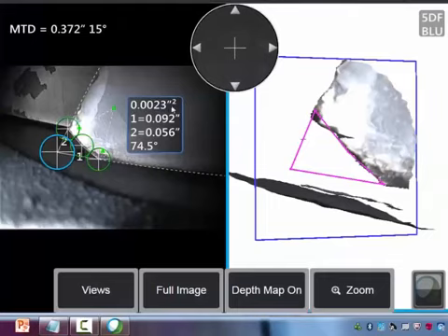And we not only provide the missing area, but we're also giving you the length of these 2 missing edge regions, which some of the maintenance manuals will call out instead of the area itself. And we also give you the angle of this missing corner.